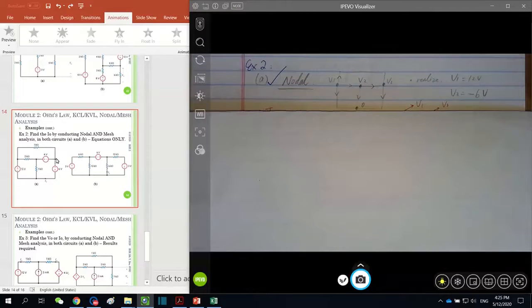For the same reason, the voltage at node 3, V3, equals -6 rather than +6, because the positive polarity is the ground and the negative polarity is at V3. So if you are fully aware of two node voltages, then the rest of the KCL equations are easier.